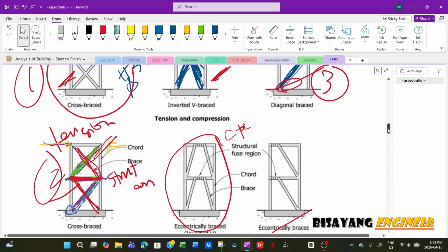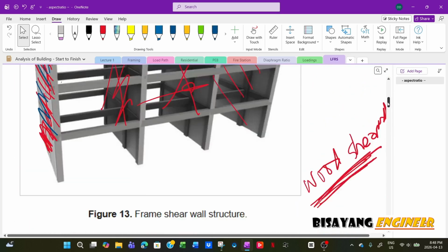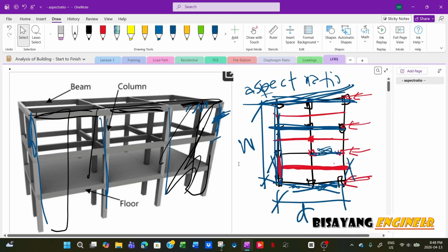And yeah, so like I said, to recap, first thing, determine the load path before you even start modeling or applying the load to your structure, so that all the loads are transferred properly and correctly. I think that's it for now.